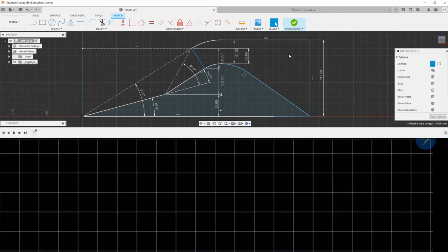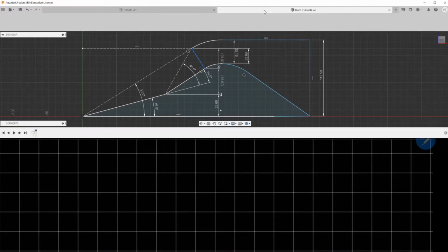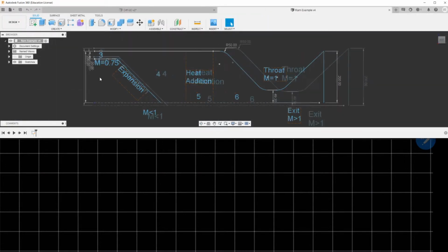How to understand if flow will be supersonic or subsonic? I think you read the chapter on nozzles, diffusers, and wind tunnels, and you will understand in which cases flow cannot accelerate more, even from Mach 1 in a divergent cross-section, cannot accelerate anymore and will stay subsonic. This is also possible. Answering simply to this question, we just need to have a big enough pressure inside the combustion chamber.